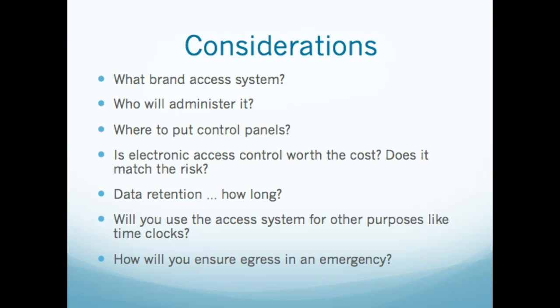I'll keep calling them control panels or controllers. That's a big decision because people tend to put them sometimes up in a false ceiling, but then in order to work on them, someone has to get on a ladder. Other people put them too close to the ground, and they put them on a wall in an area where they keep getting banged into by forklift operators and people moving heavy equipment and all kinds of things and do damage. Where you put them, you need to consider how high up on the wall you want to put it.